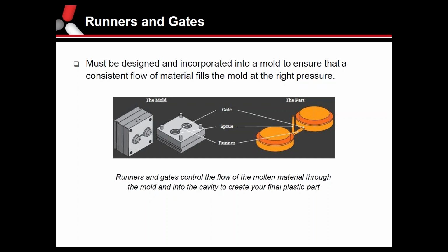But there will be some sort of cosmetic marking on the part. And hot tips and actuated delivery systems in tools will help with the vestige. They're much cleaner, a little more expensive to design into your tool, and require a slightly larger tool. That's also just something to consider when you're looking at the aesthetics of your part.